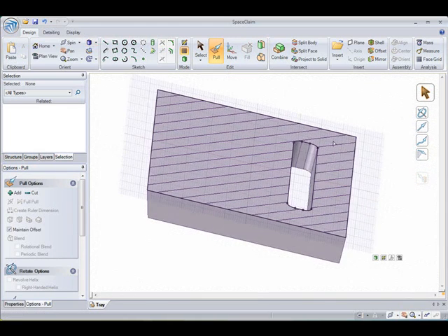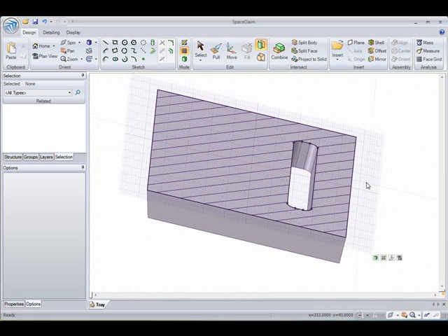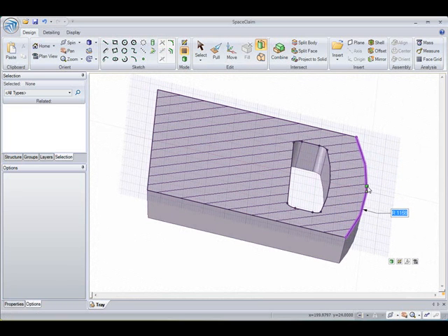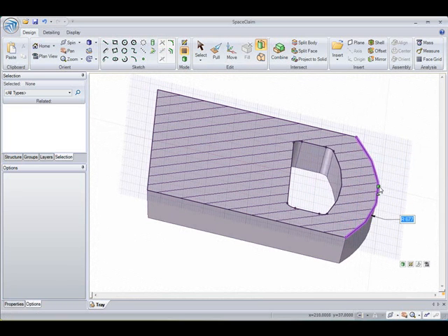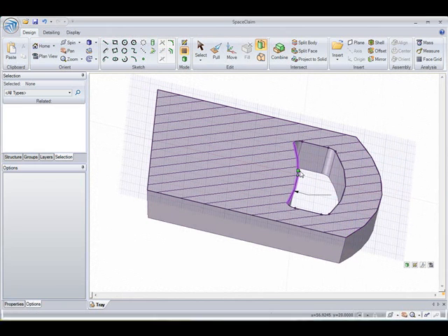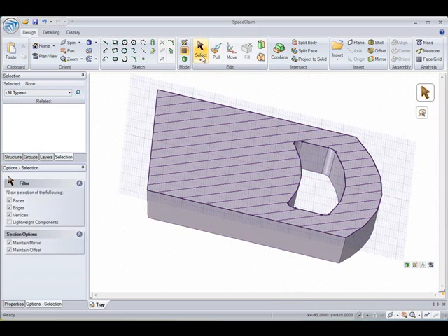But now let's add some more contour, and we'll do that with our bend tool, which allows me to bend a straight line in a section or a sketch into a curved line. So I'll bend it out and I'll type in 600. And notice that when I bend out the outer one, the offset wall bends as well. Now I'll do the same to our inner wall and bend that 600 too.